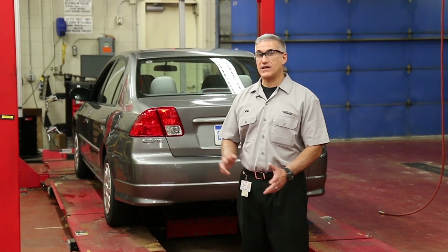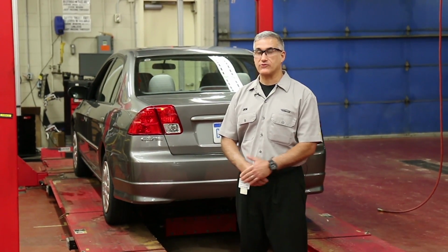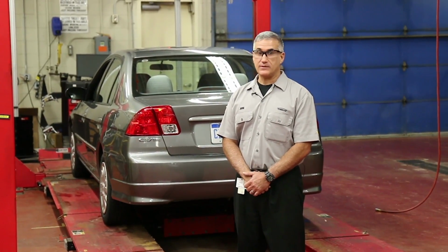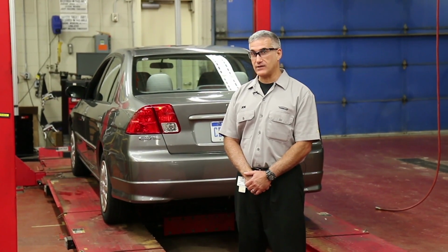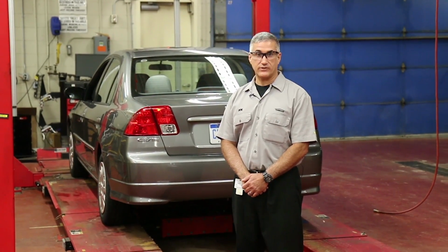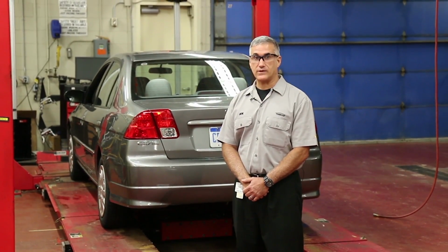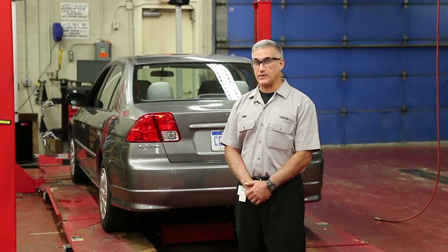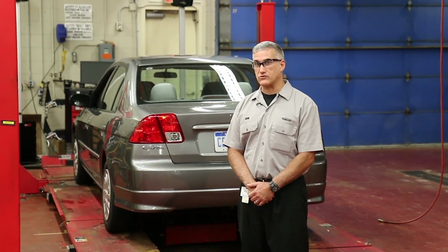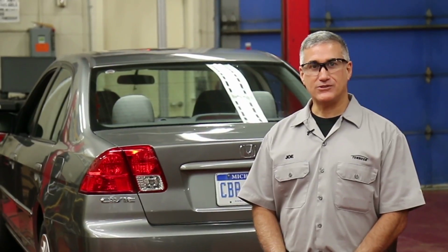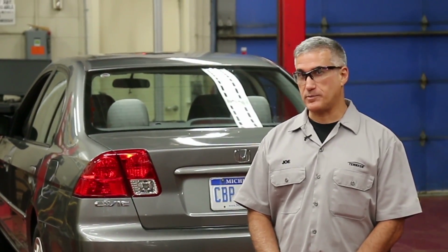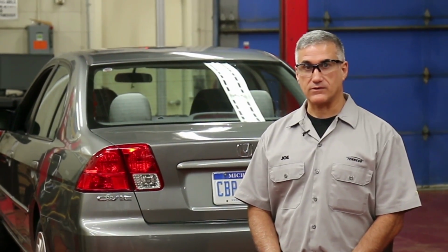As an example, there's not one standardized measurement for all vehicles, and many manufacturers don't supply ride height specifications for many of their vehicles, since they know that modern spring designs can support the weight statically, but the vehicle may see an issue dynamically as it drives down the road. So there are two steps to determine if the springs are doing their job. First, you want to measure static ride height. Then we want to inspect for dynamic ride height concerns.